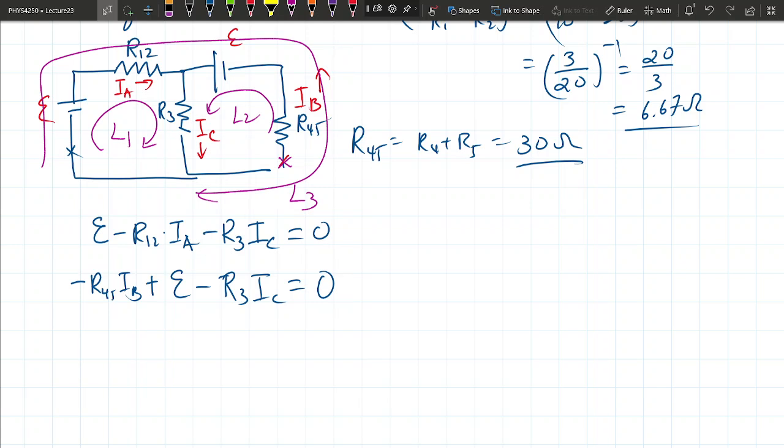So IA and IB are both going into the junction, so they should add together and make IC. IA plus IB equals IC. You guys see that? If I had declared this current to go downward, then the placement of these would be different.